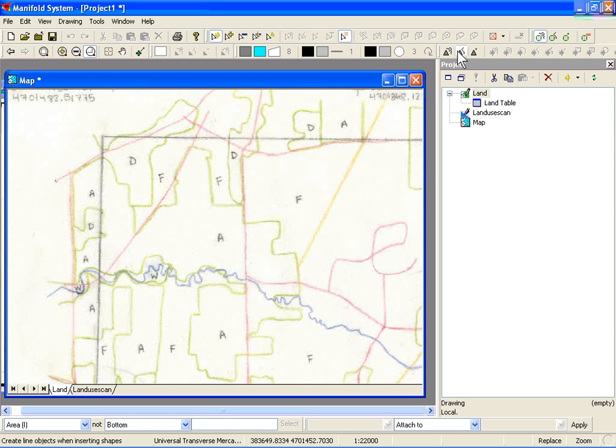For this part, let's select the line and the Insert Line tool from the toolbar, and we'll begin to digitize the boundary lines. Let's start with this developed polygon first. Again, hitting the left mouse button to follow each of the lines, and then the right mouse button to end a line. And we're going to overhang the lines just a little bit from the outside, and we'll clean that up later with the topology tools.